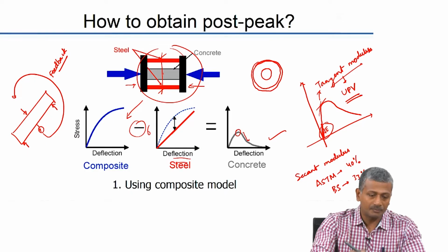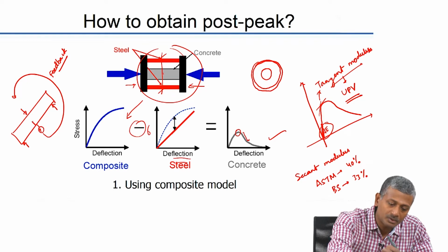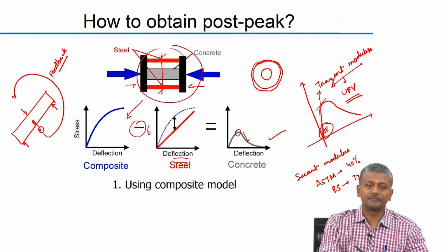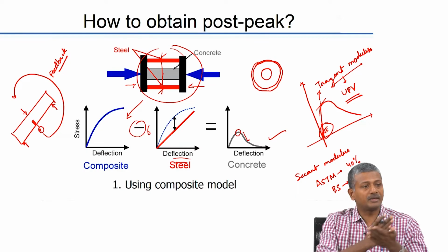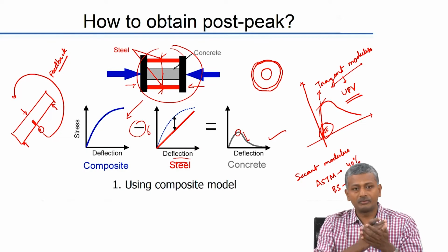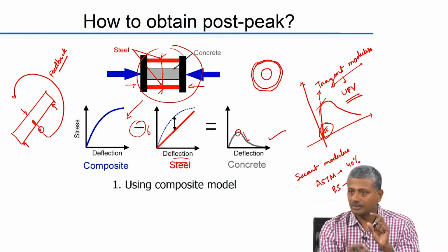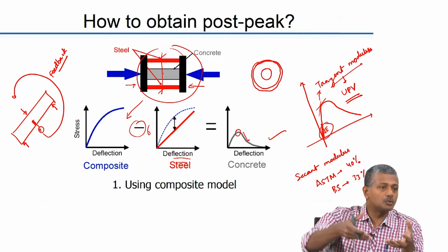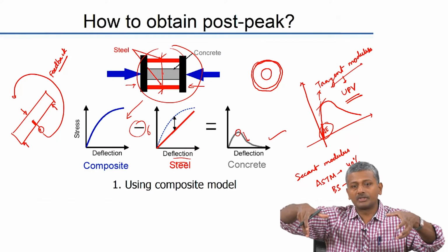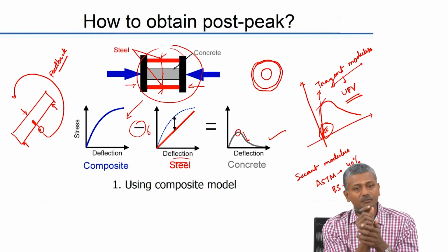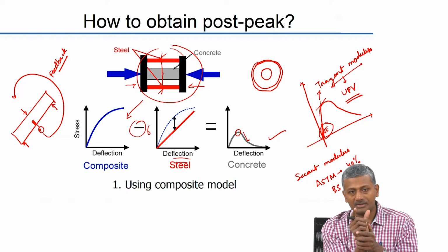Okay. In fibre reinforced concrete, one of the other experiments that you may see apart from the regular ones that I have described here is the same experiment done with a notch in the center. You create a notch by making a slice in the center, which is up to a certain depth, not up to half the depth, but less than half the depth, and then when you do the flexural loading on this material, what will happen is the crack width at the notch will keep on increasing.